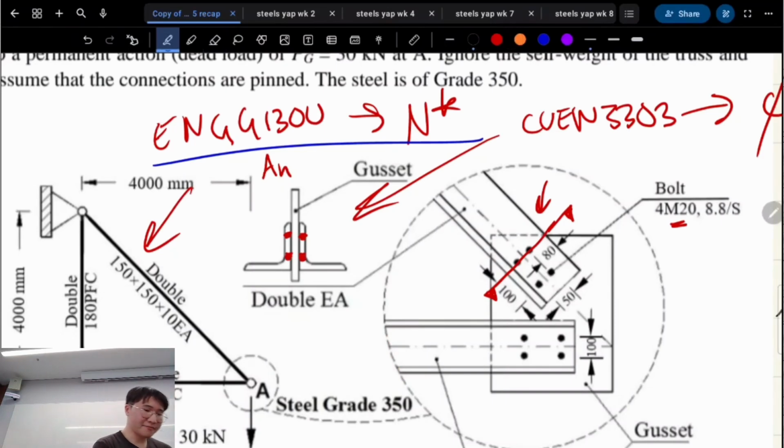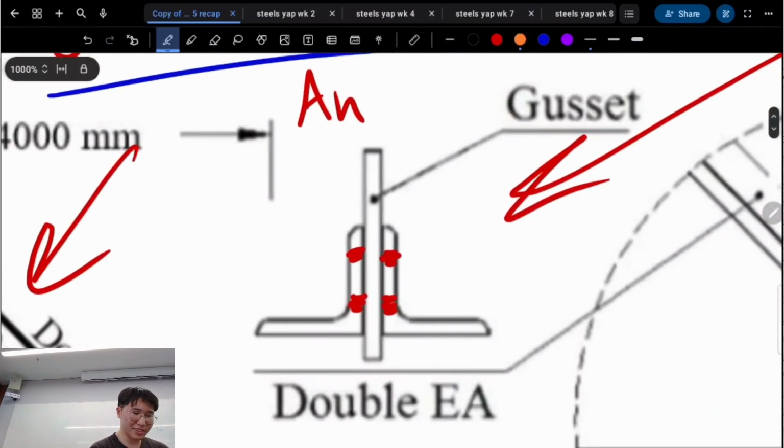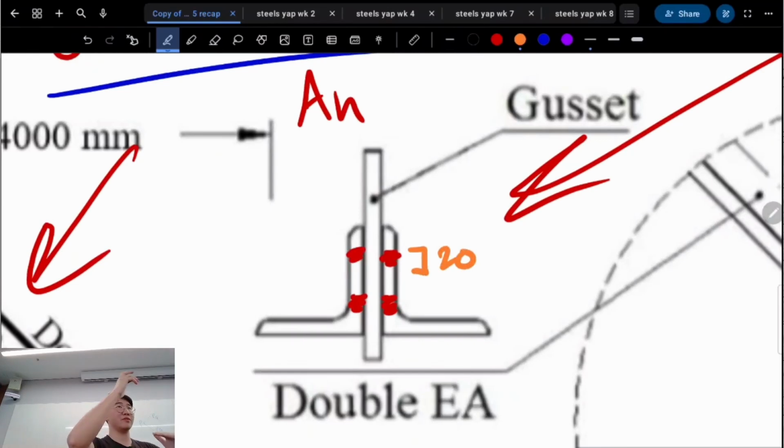Okay, so let's look at these bolt holes. The bolts themselves were 20, right? We said 20 bolts. What we say is on either side of the bolts, there could be an installation error or a bit of wiggle room because of where the threads go in, right? So you have 1 mil on either side of that, which you increase that whole diameter by. So we just add on 2, right? So if you have M20 bolts, 22 mil for the whole opening.